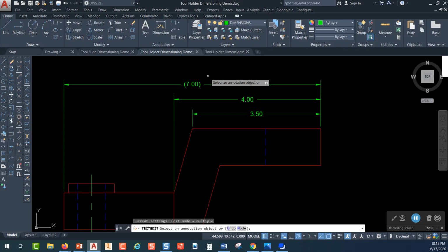They should not put any tolerances on this, because they have other dimensions they can use to make the part where they'll apply the tolerances. One of those dimensions is 4 right here, and then we also know there's a dimension from this corner to the center of our hole right here, and then we know the radius to the end.